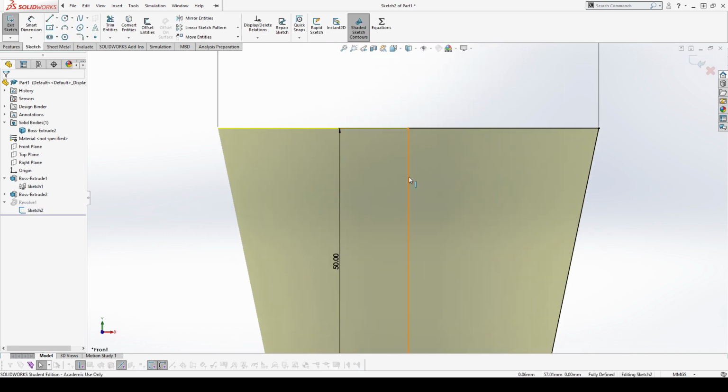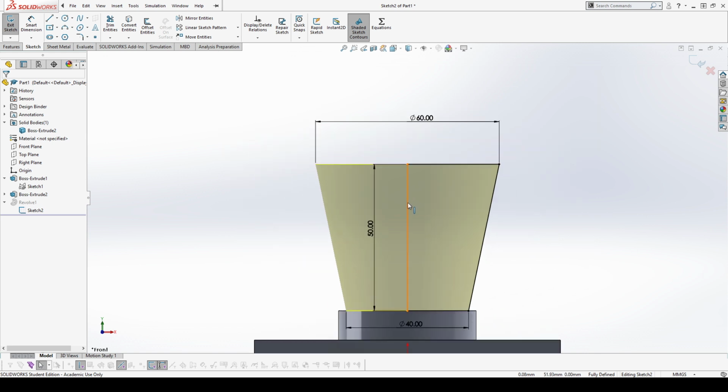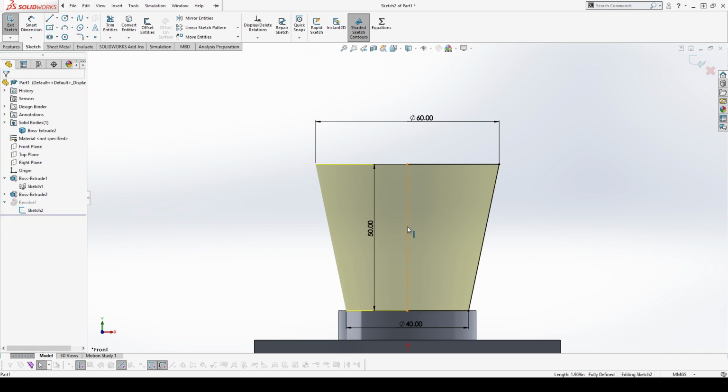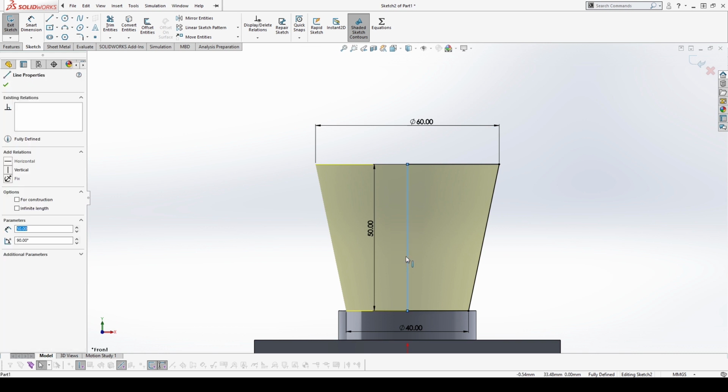By opening up that sketch, you can see that we created this line, or SolidWorks automatically went in and made this line for me. If I delete it, we can bring back that construction line that's right behind it. That brings up something that's important. If you can't select the thing that you want to select, because in this case they're right on top of each other, you can right click and you have the option to select other right there.